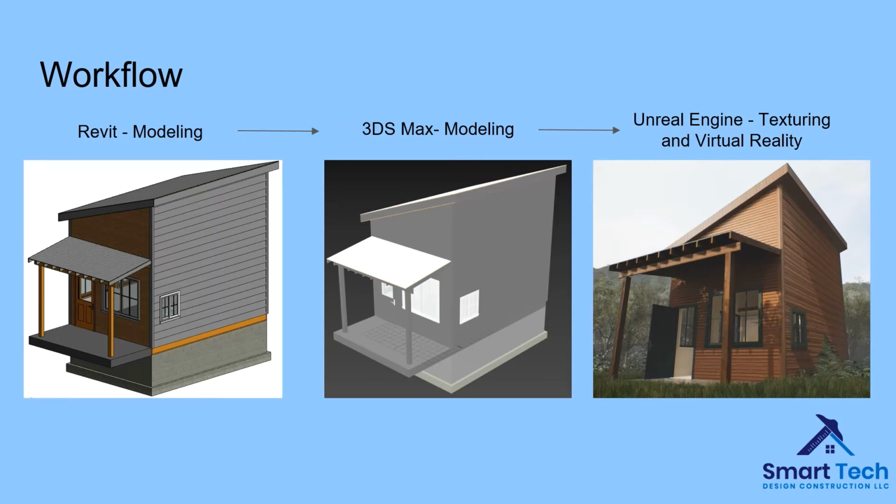So, a mile-high overview of our process was to do all of the rectangular modeling in Revit, which comprised 99% of the modeling. However, the last little bit had to be done in 3ds Max due to the triangulation of everything modeled in Revit. Essentially, anything that is curved was modeled in 3ds Max to improve the performance of the project when viewed in virtual reality.